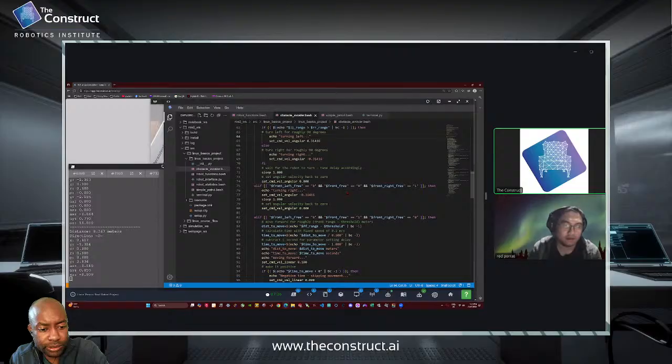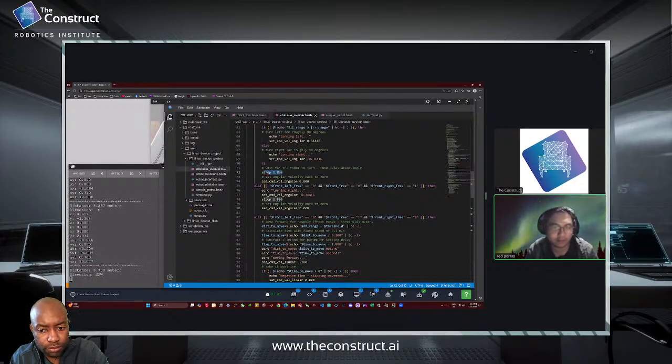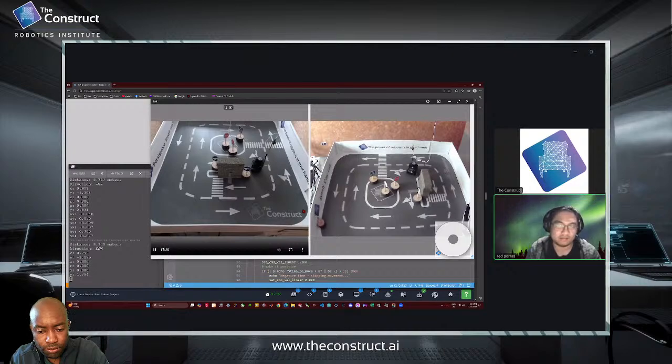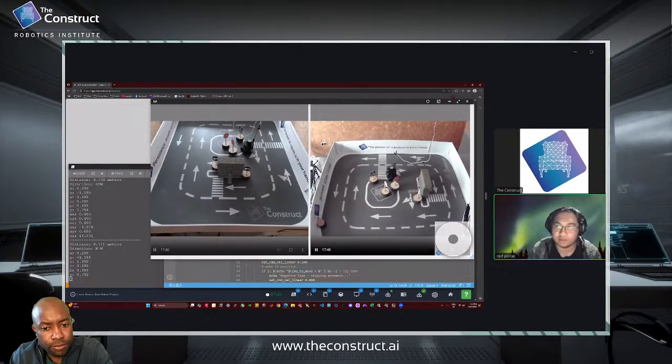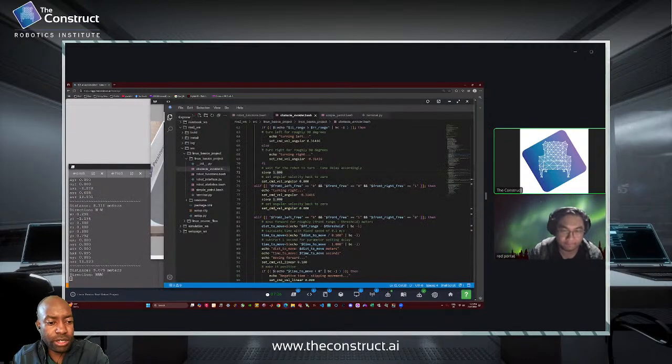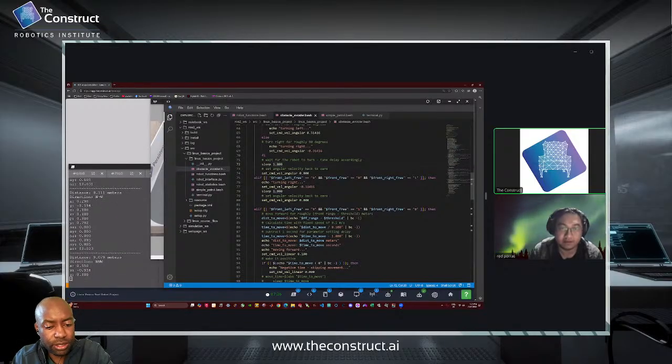Can you explain that? For this one, I just tried it multiple times, because sometimes when I put 1.6, which is the same as the simple patrol, it gets stuck in the corner. If it's stuck here, for example, it's just rotating, I think 30 degrees, and when it rotates, for example going right, it will go here. Then it just keeps rotating left and right if I put 0.6 or below. I'm not sure about 0.7, I haven't tested that. But when I use 1.0, even if it's at the edge, it's working now. It keeps moving forward in a different direction. That's why I put 1.0. So you had to try different values to figure out which one works best. Yeah, that's what I did.